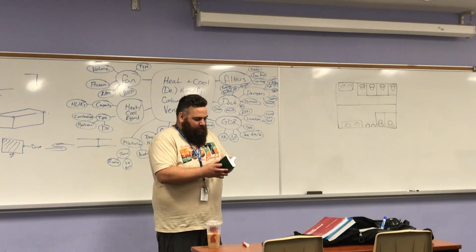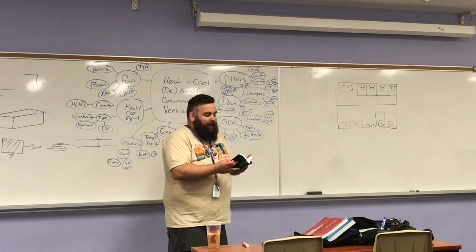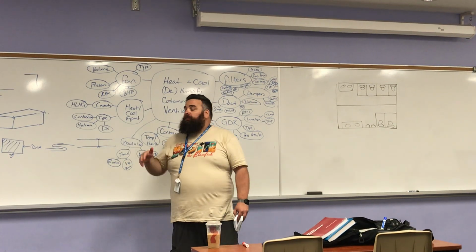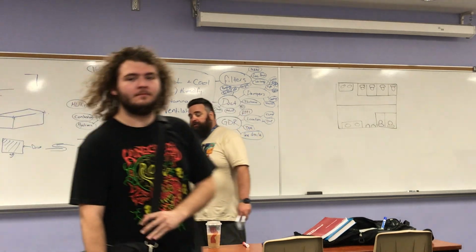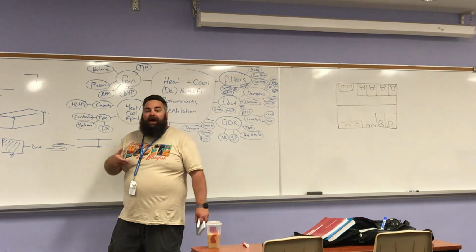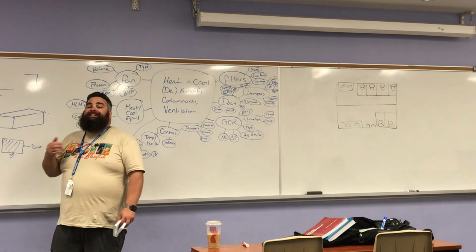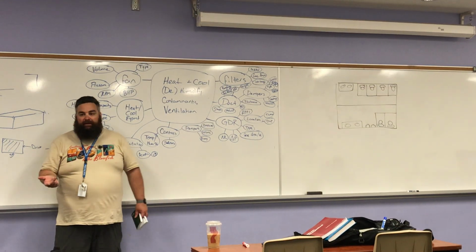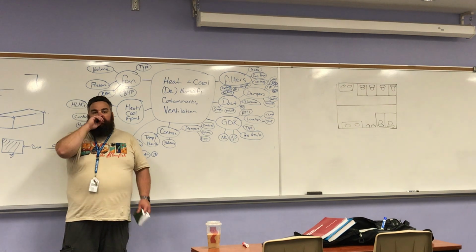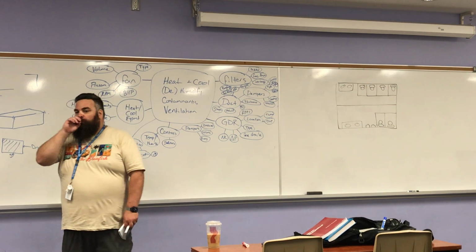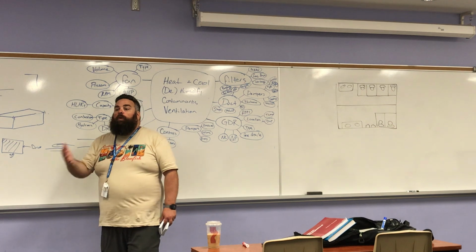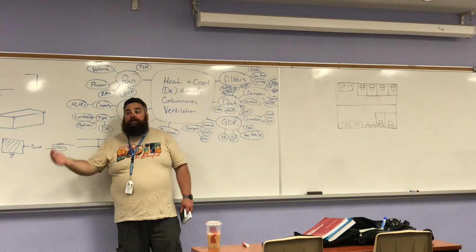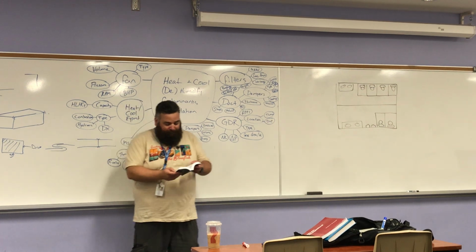Okay. So the things we want to know out of ASHRAE 62.1, there's a whole bunch there that we're going to get into later, but the immediate concern is how many CFM of exhaust do I need, or how many CFM of outdoor air do I need, and what is the class of air. The class of air refers to what kind of contaminants are in it, and what can we do with it. How close can we discharge that to an intake? Can we filter it and send it back into the space?